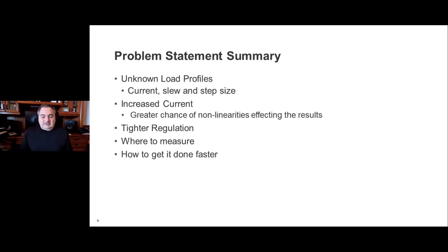So the phases on the outer edges, if you're looking down on the board from the left and the right-hand side, are at different lengths than the ones in the middle. So they probably have different trace inductance, power plane inductance, and series resistance associated with them. So they're going to, by definition, have different thresholds for when they need to be activated and not activated. You think about these solutions, as you add a phase or remove a phase, when the current goes up and down, these phases are shared on.